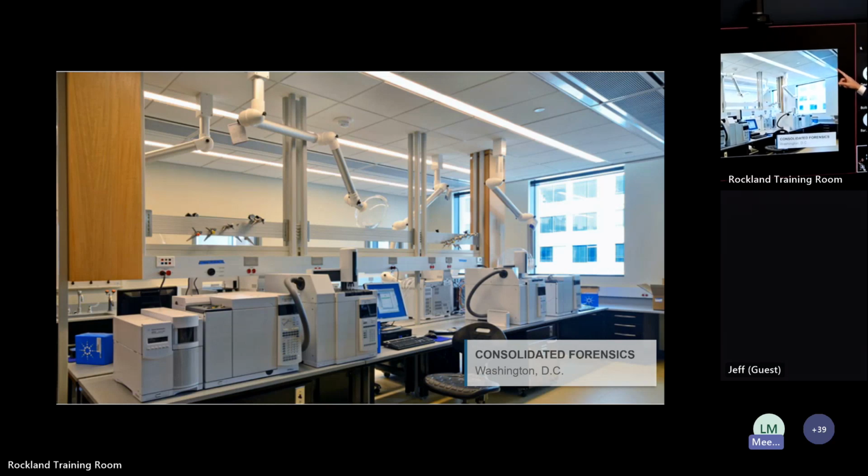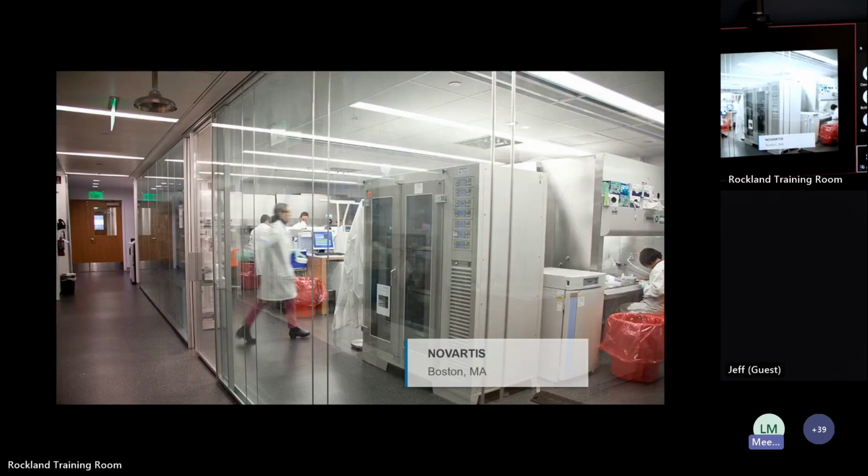We've got continuous linear beams up in the ceiling. They're located above the aisles, and 2-foot grid, about 8 feet across. So just a lot of the software tools, including the price software tool, allows you to look at throws and collisions based on the distance you're placing them throughout. So if you haven't seen that before, we'll try and walk through that in the afternoon. There's also pattern controllers as well that can orient the airflow to be shorter or the standard throw distance.